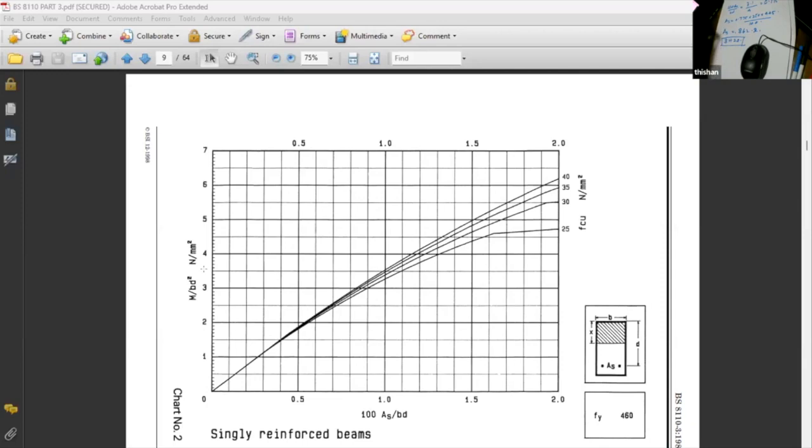If you need, say, 200 millimeter square steel, then you have to provide it. So select the correct welded mesh. Welded mesh, no special rule. You calculate the reinforcement and use the same area from the welded mesh. That's all.